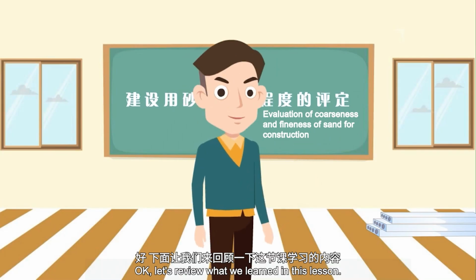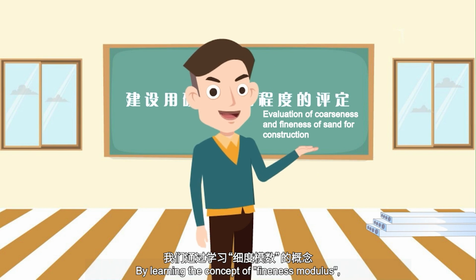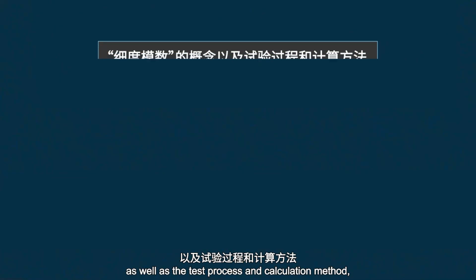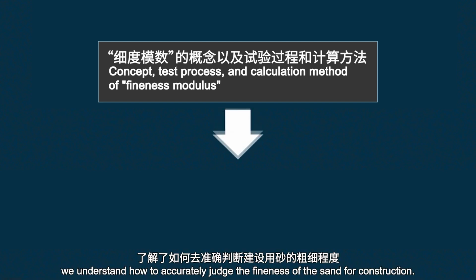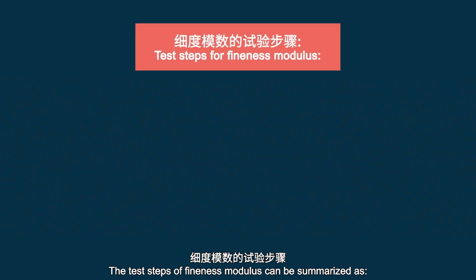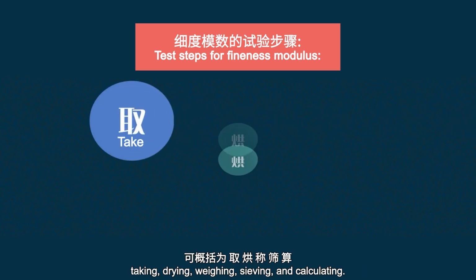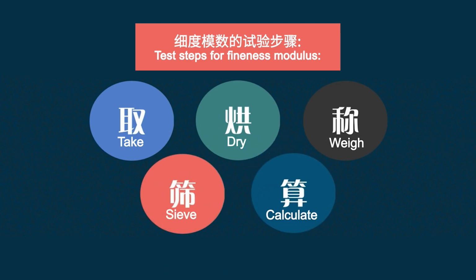Okay, let's review what we learned in this lesson. By learning the concept of fineness modulus, as well as the test process and calculation method, we understand how to accurately judge the fineness of the sand for construction. The test steps of fineness modulus can be summarized as taking, drying, weighing, sieving, and calculating. Have you now got it?